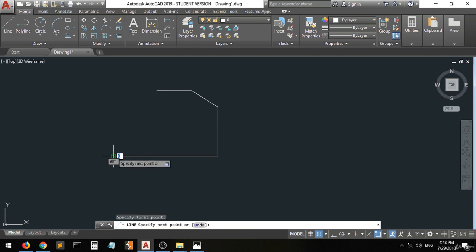So as we said, we will move what? 0.25 in the vertical direction. And again, you can use whether the coordinate entry, the relative coordinate entry, or the polar entry. Anything you think it is easier. So I'll do it in the polar. At 0.25, since it's going on the positive direction, right? Then we'll do it in angle of what? 90. And then we have this.